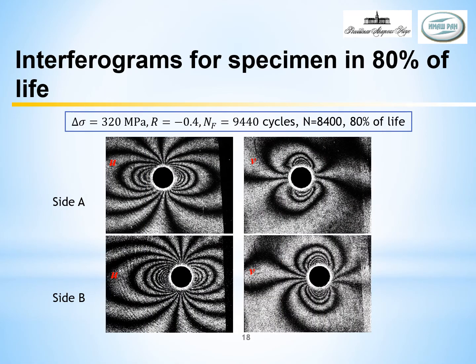The deformation response to secondary hole drilling, expressed in terms of interference fringe number, evidences that residual strain relaxation in the longitudinal direction, coinciding with the applied force line, exceeds relaxation in the transverse direction U.